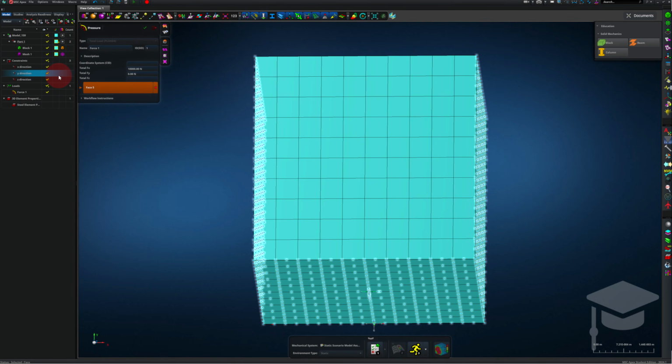The picture that I showed earlier with a single arrow pointing along the top of the block was a little bit of a trick because in truth, pure shear loading requires arrows going in multiple directions to be able to give a balanced state of stress. Still, this corresponds to something physical that's meaningful, like the sole of a shoe is using shear stress to propel somebody forward, but it's not really under very much bending because the sole is very thin compared to how wide it is. These left and right hand boundary conditions approximate that effect.